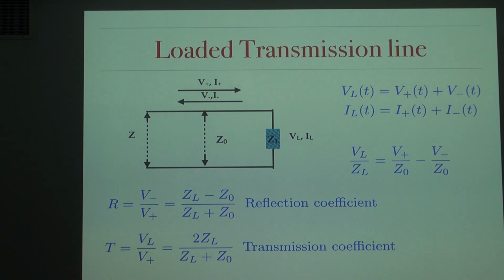Now it is very easy to see that if we have the system where the impedance of the network is very, very small as compared to the complex impedance of the load, then the reflection coefficient is essentially 1, because the numerator and denominator cancel. And if the impedance of the load is much lower than the impedance of the network, then the reflection coefficient is equal to -1.